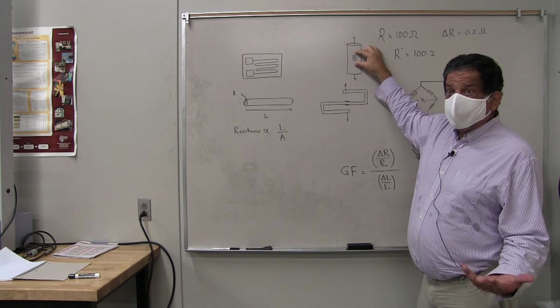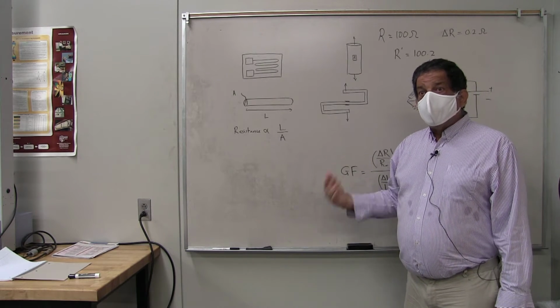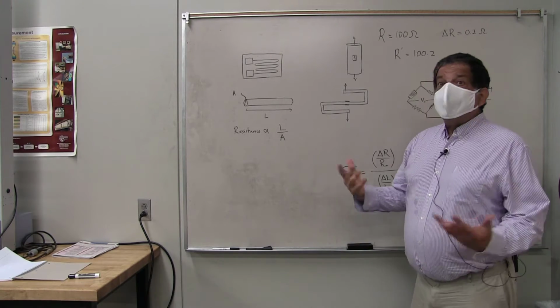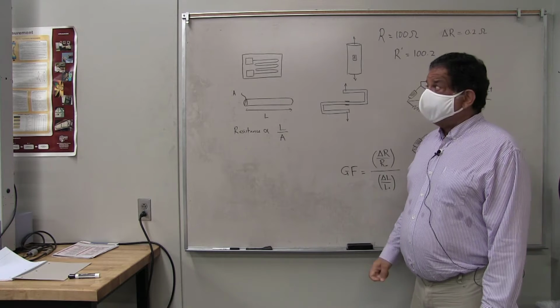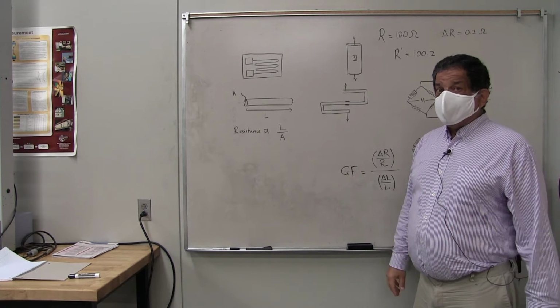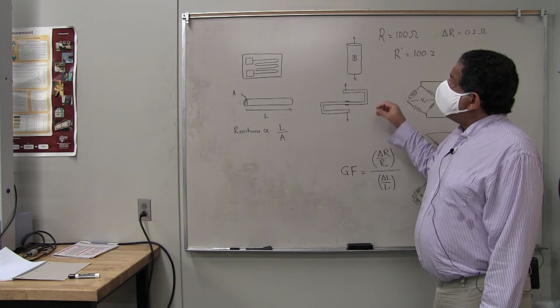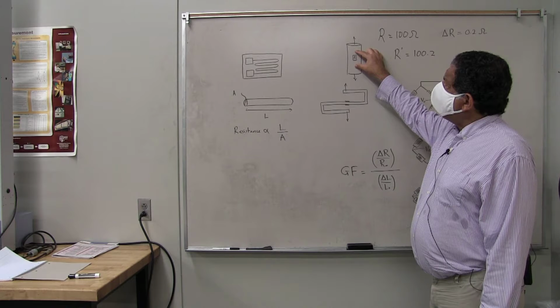If I have a smaller deformation, which is what you typically have during normal loads that are applied to a structural member, then you'd have even less than that. So let's say I have 0.1% strain, which is a typical elastic strain. That's actually a fairly large elastic strain for most structural members that are made out of metals.